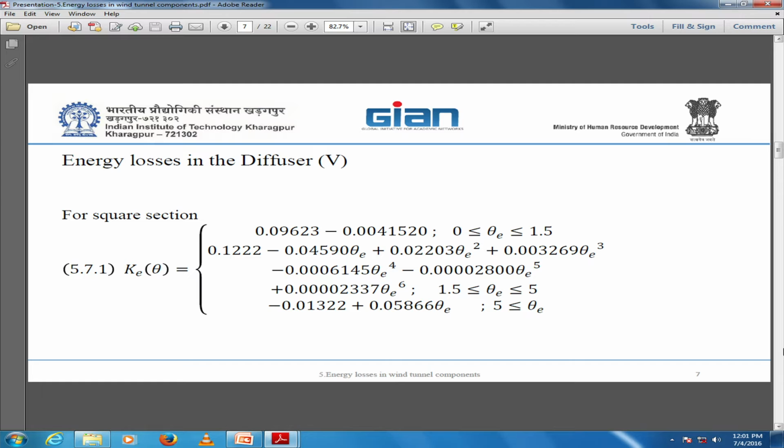In one place you find somebody giving an angle of attack to those turning vanes by cutting the metal a bit shorter. If you shorten one of the edges of the corner, you get an angle of attack. So in one of our wind tunnels in Tel Aviv we made it 4 degrees, and elongated the trailing edge.